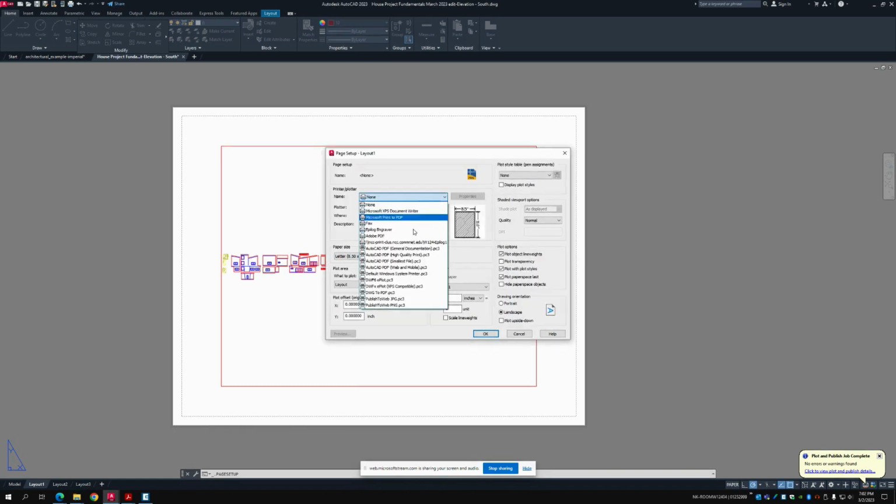And then I'm going to go to the DWG to PDF printer/plotter configuration file. This is a file that is local to your machine, so do keep that in mind. Whenever you change this setting on your computer, it's going to be only changed for that particular computer. So try to keep that in mind when you go to log in again or print out more of these PDFs, that you use the same computer that you used when you changed this configuration file initially.